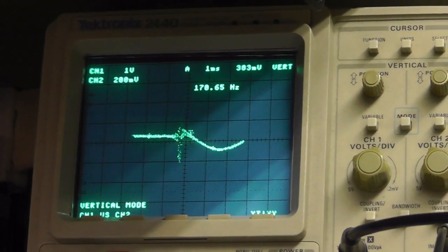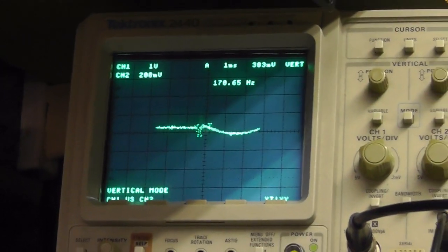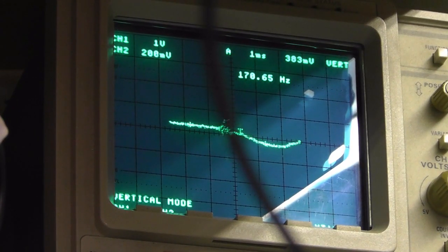Often takes a bit of adjusting of RF levels. You've got to get the RF level down as low as possible. Obviously, we don't activate the AGC circuit. So let me just try and set this up so you can see what's happening. Right, I'll talk you through roughly what I'm doing.